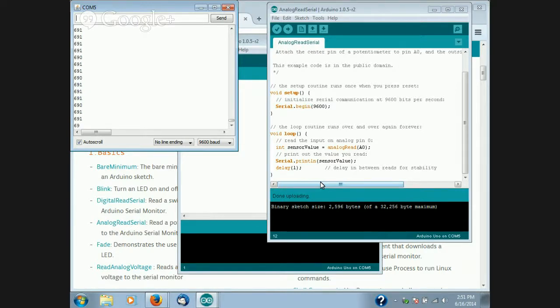Anyhow, we were just illustrating. This is 3.3 volts in, and the digitizer calibration is drifting over time. That is 5 volts in, and that's maxed out at 1023, that's saturated. And this is ground in, so we have 0 as the output.